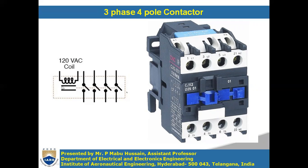Some manufacturers give the coil voltage as 120 volts AC, some give 220 volts AC, or even 24 volts DC. So first you have to observe the specification sheet of the contactor, then decide the voltage rating of your coil, and apply only that particular voltage.